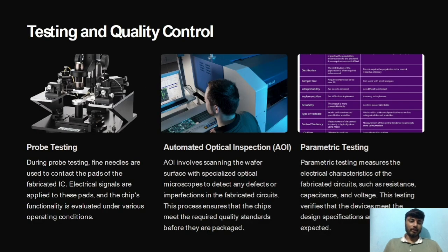Testing and quality control. Probe testing. During the probe testing, fine needles are used to contact the pads of the fabricated ICs. Electrical signals are applied to these pads and the chips' functionality is evaluated under various operating conditions.